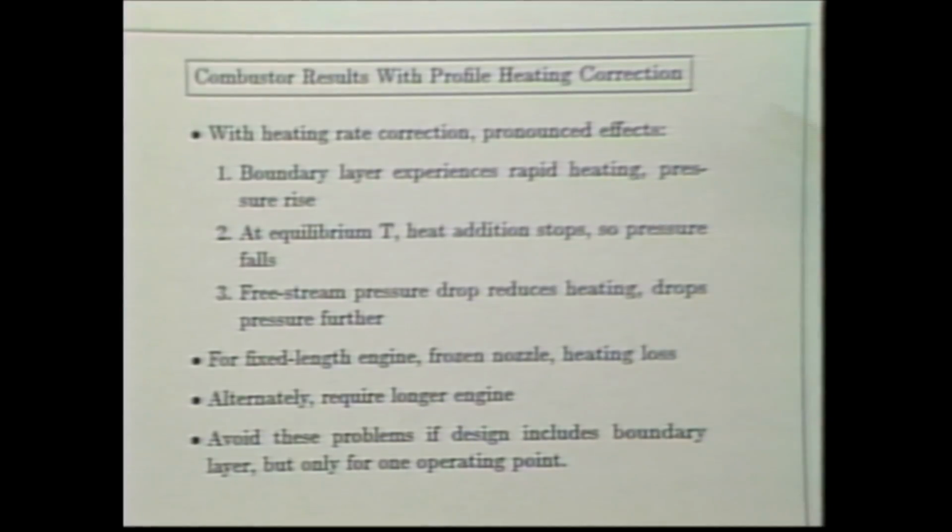Okay. What happens if we put a flow profile into a hypersonic engine? Several things. One of the things we find is the boundary layer experiences very rapid heating, very rapid pressure rise, and after that, combustion stops in the boundary layer. So by and large, some simple models indicate that you don't get much energy released in the boundary layer. What that means is, if you want combustion to proceed, you're driven to a longer engine, which is a heavier engine, which is something that the airframe people don't like.